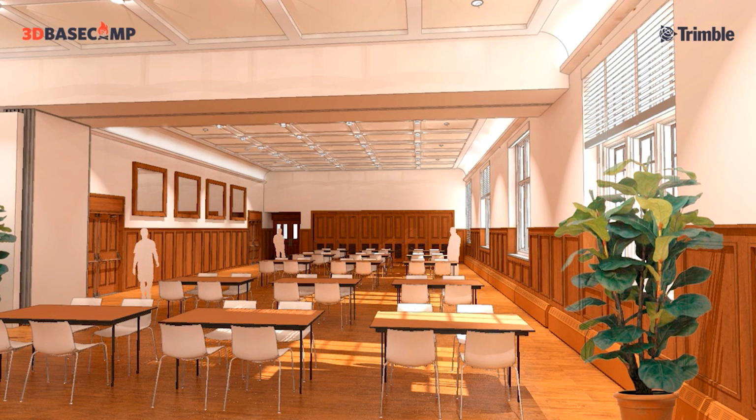So a lot of times I'll take that original SketchUp model, bring it into Podium, and just kind of light it up with Omni lights and some of the presets that Podium has, just to kind of give a sense of, we want to put tape light up here to wash that. These are downlighting the wall and washing the wall, and then the center lights have direct and indirect light there to kind of light up the space.